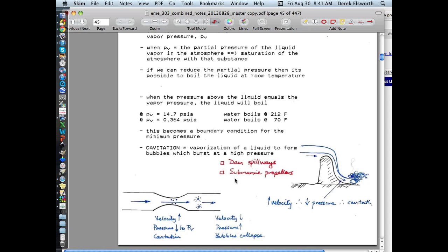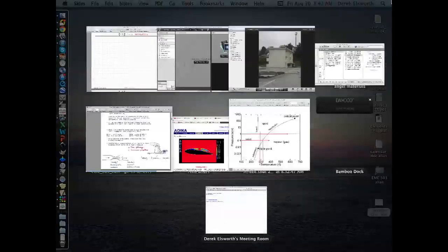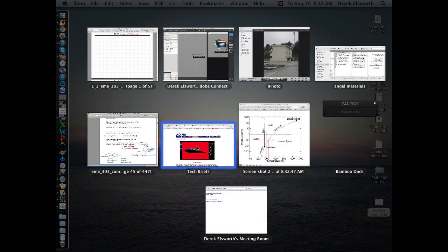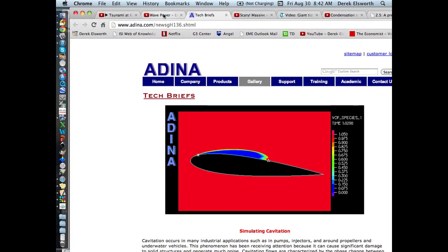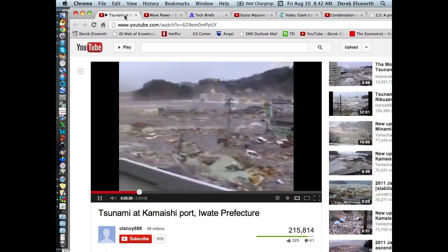If you want to run deep and silently, you don't want that to happen. So you have much larger blades, almost like the propeller of a plane, which move much more slowly, and as a result, they don't have any of these cavitation effects. So, again, I won't show that here, but that's the reason for that.